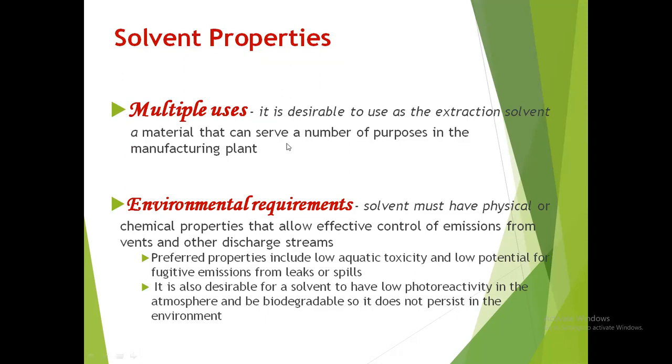Okay. The multiple uses in terms of solvent properties is more on the economic side. So we want, as much as possible, our solvent to be recoverable, recyclable, and reusable in other parts of the process. But there may be specialty solvents that cannot be used or reused in other parts of the process. What is important here is that it could be recovered and as much as possible reused in your system, with the requirement that if it's recycled already, we don't expect its purity to be the same as that which is freshly bought.